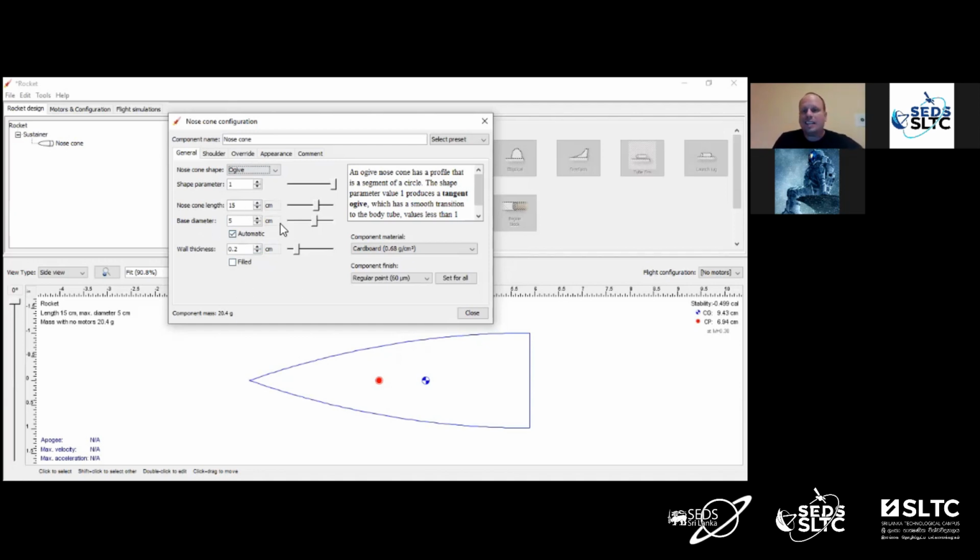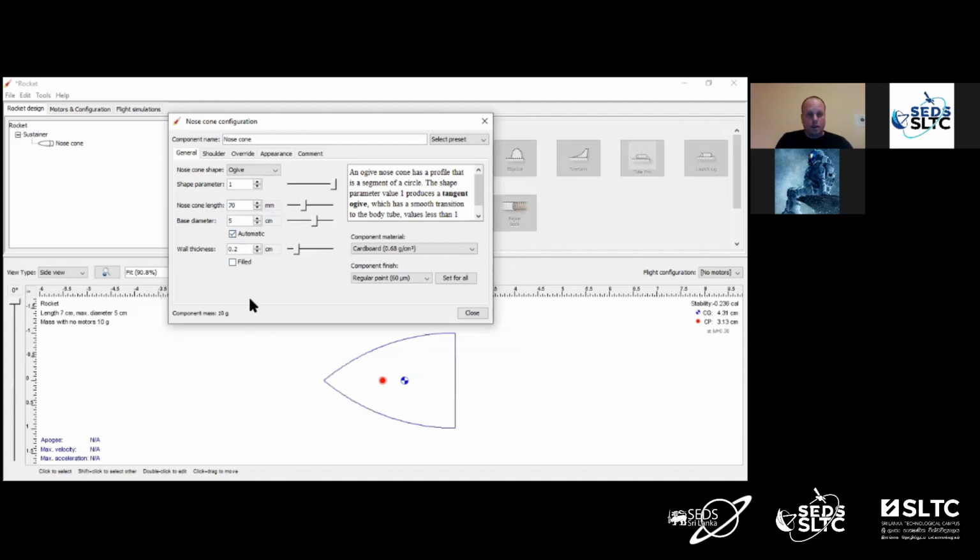millimeters. Anytime there's a unit in OpenRocket, you can change the unit manually. We set the whole default over to metric, and you can individually manipulate each unit too. So for example, for nose cone length where it's got centimeters, I can just click the unit and it gives me a list that I can choose from. If I choose millimeters, I can make that whatever I want. Just double click it and highlight it. So put that in there, go to the next thing.